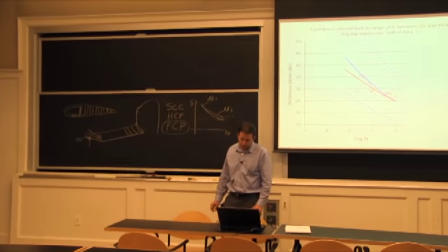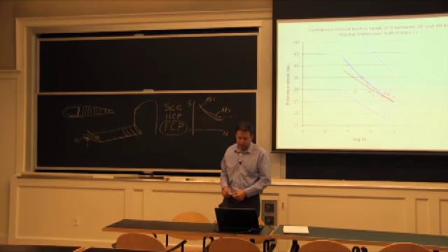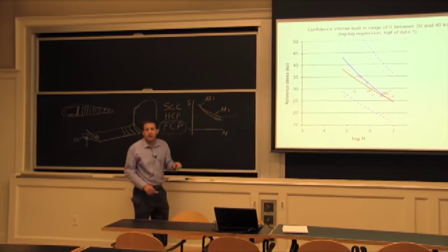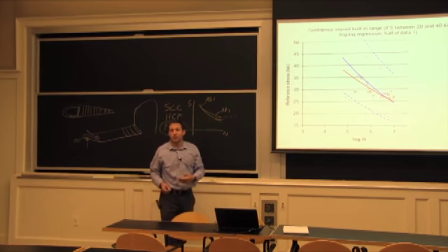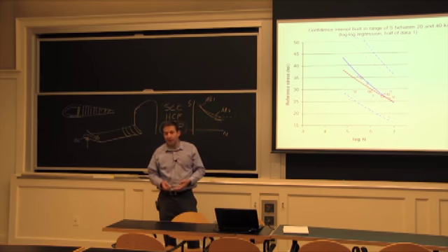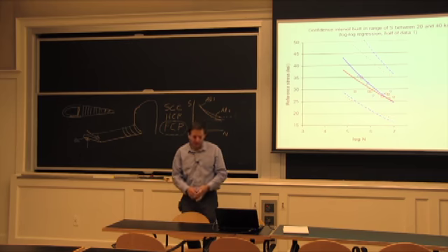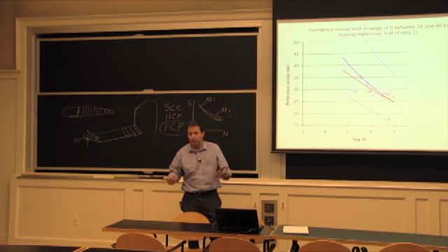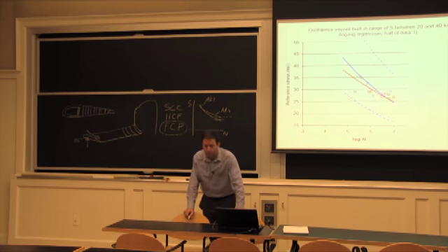And that's really one thing I'd like you to take out: in aerospace, you don't take these curves for granted. You have to go a step further and look at how they were generated and the variability that's associated with them. And when we talk about the landing gear having a safety factor of 1.1, 1.2, it's because they've already knocked it down based on actual data. So they went with more testing than you'll do in building up a trailer, just to be able to know that their safety factor is just 10% or whatever.